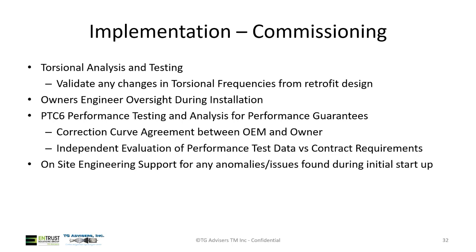So after the manufacturing process, you move on to commissioning. So you need to be lined up for, if you did the torsional analysis and it said that you needed to do testing to confirm whether you're safe or not, make sure you do torsional testing during the commissioning process, validate the changes in the retrofit design.